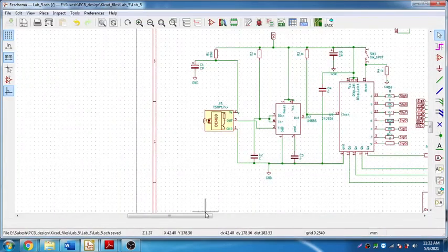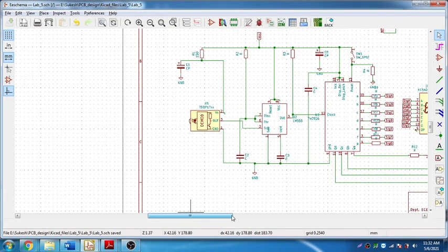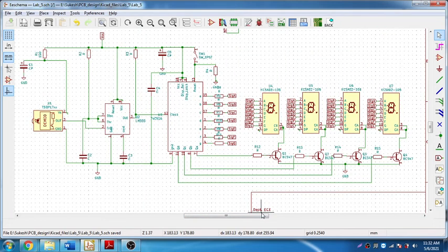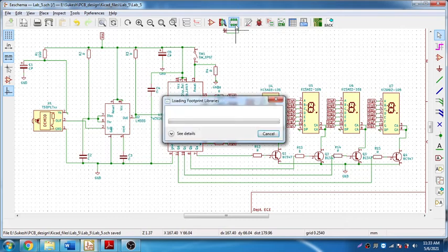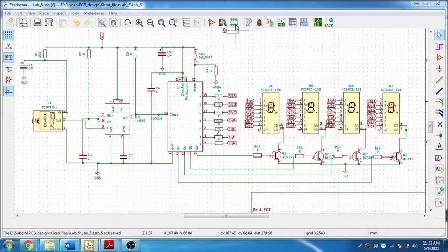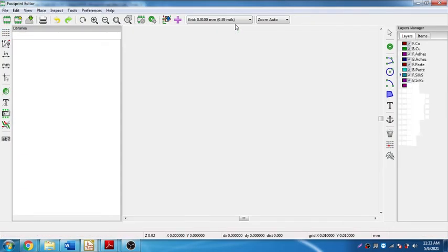Okay. So we need to design a footprint for two of the components. That's now our main job. So what we do here is we'll simply go to create a footprint. For that you need to click here, footprint editor. Okay, just select here footprint editor. It will open a library for you of available footprints, and now here you need to create a footprint.